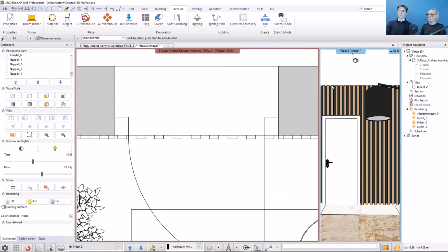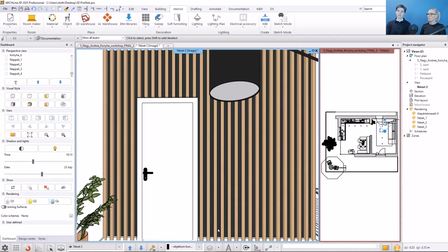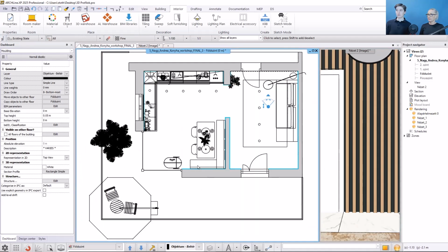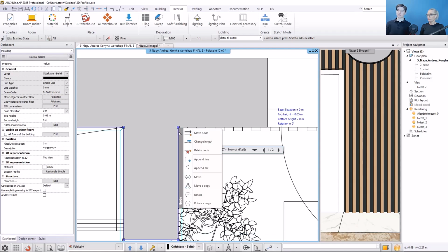ceiling. Now they are in the right place. Yes, but the skirting boards and ribs intersect. How will you fix that? I will delete the joints on both sides of the door and pull back the ends on each side, so the skirting boards don't intersect with the ribs.